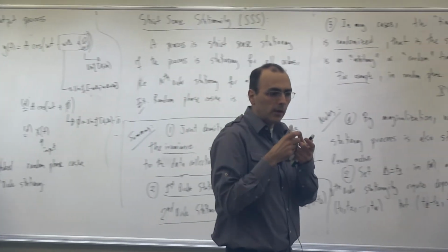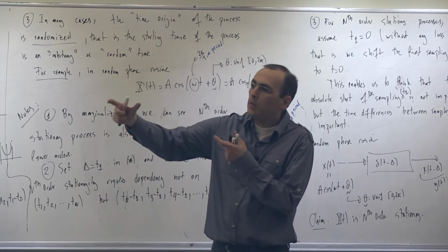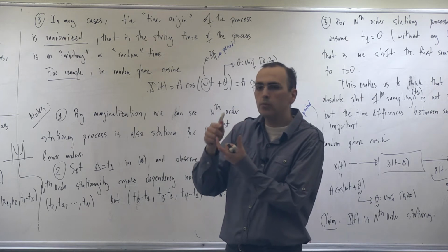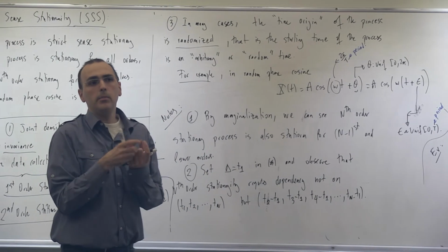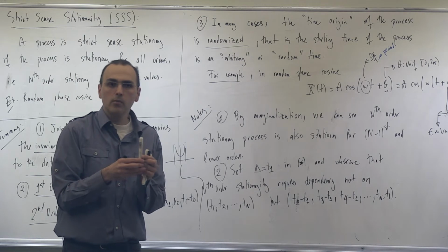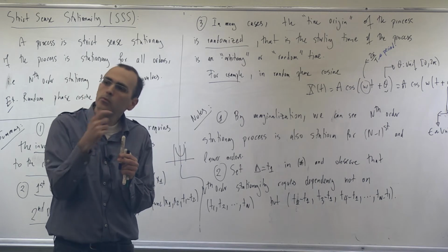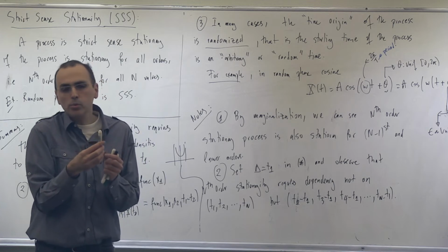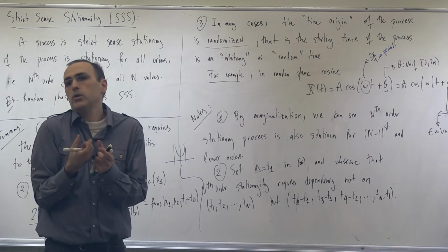When you have such a delay, please remember the wave propagation: every wavelength lambda of propagation in the propagation direction corresponds to a phase change of 2 pi. That wavelength may be in centimeters, in millimeters, and so on. So if I move my antenna 1 millimeter to the left or right, it can be half a wavelength. If it is half a wavelength, then the phase changes by pi. Do you see what I mean? So you cannot control your antenna, or let's say the target location, precisely.